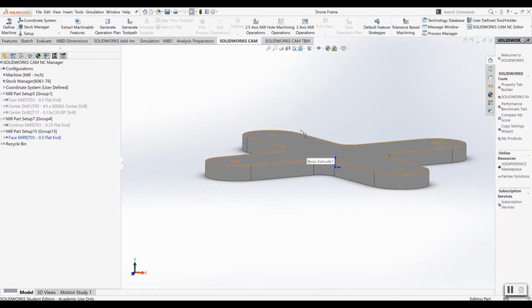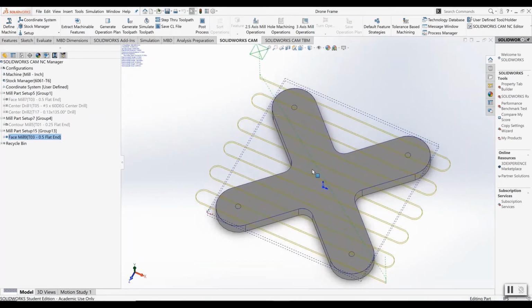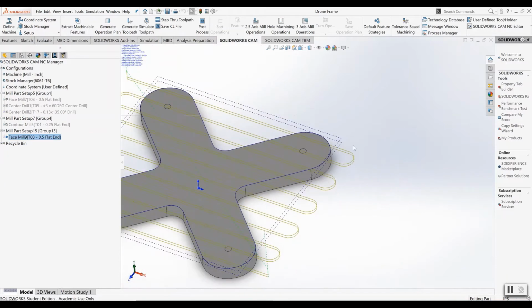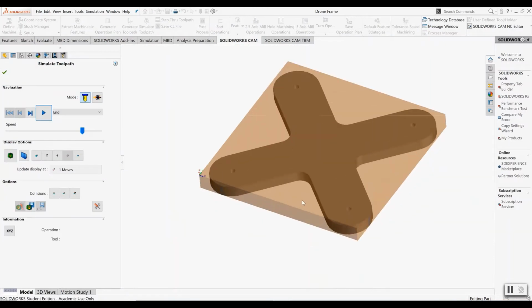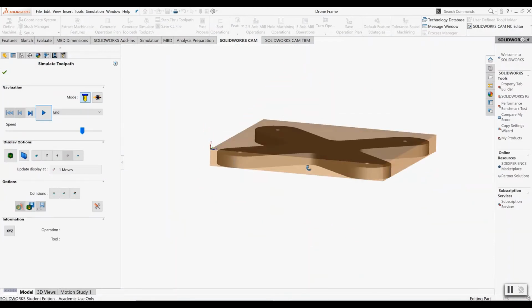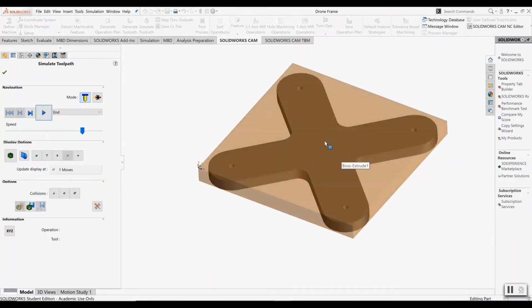However, there's no toolpath. So what you want to do is now we can generate a toolpath with this selected. So after generating the toolpath, you will see the physical toolpath that the cutter goes over the part with. There are 2 lines and the tool will go over it twice. And if we simulate the toolpath, then it will create a box around the part, and that shows the excess material of the stock, and the darker is obviously the drone frame in the middle.